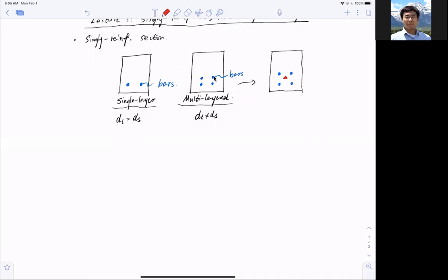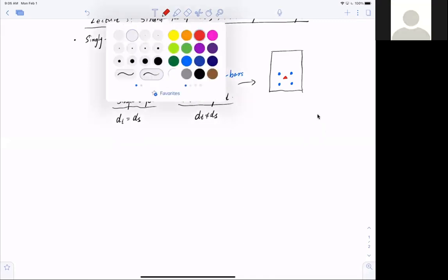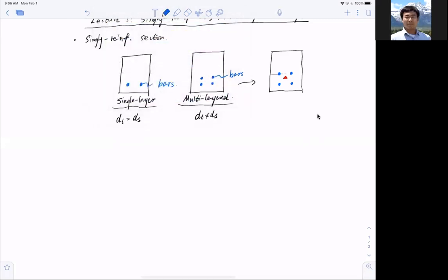And we also know that I have to use my first moment or static moment to find the distance. So if this is the first layer, and I have the distance between the first layer to the bottom reference line, I call it D1, and the second layer is right here, and this is distance D2.